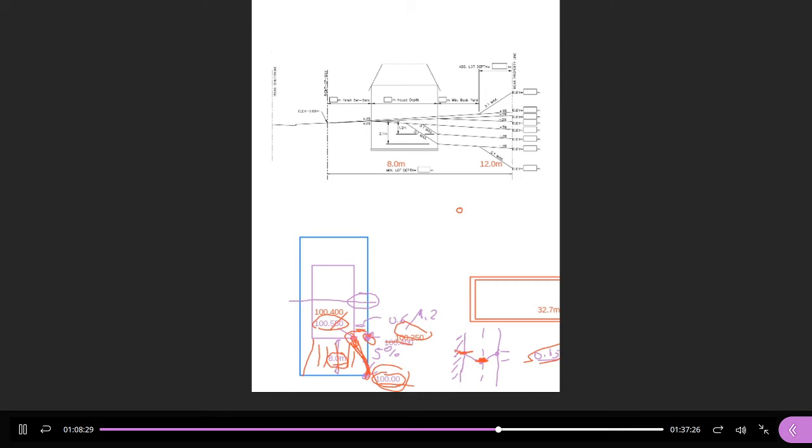So start at the front, 0 elevation. Go 8 meters for 2%, whatever that number is, and then subtract 3% of 12 plus 7.5 plus 5.2. Right? So 2% of 8 gives you the elevation at the front of the building. And then from the front of the building, you're going to go all the way down to the backyard at 3%. So 12 plus 7.5 plus 5.2. Yeah, exactly. Okay. So there we are.